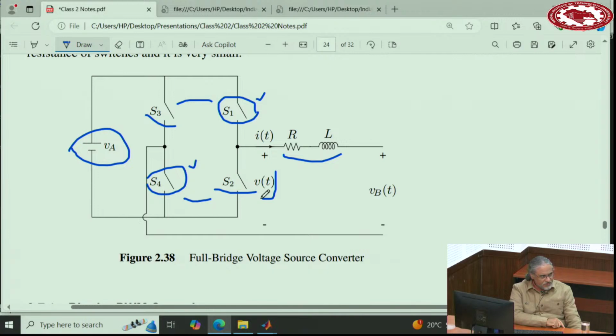Any other advantage anybody can think about? That's these two that come to my mind now. EMI, exactly. Yeah, because again, the level of the switching steps is smaller, so the EMI level is smaller. Okay. Yeah, EMI we don't teach in this course, but EMI is also very important for power electronics. So EMI lower, inductor smaller, and hysteresis loss is lower.